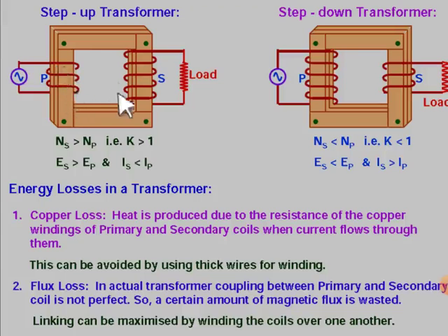No doubt here also it is coupling, but the coupling is very far away. One primary coil here, secondary coil far away. Instead of this, if the secondary coil is wound over the primary coil, then there will be a decrease in the magnetic flux losses. So your leakage of flux losses can be minimized if the primary coil and secondary coil are wound one above the other.